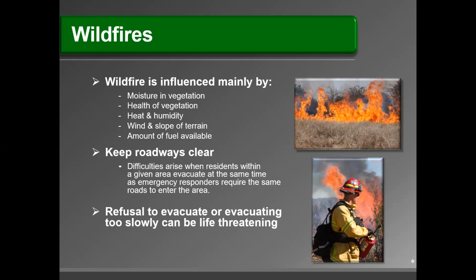And I'll tell you, as the fire department, we regulate that when we look at their inspections. They can only have a certain volume on site of a hazardous material in a commercial occupancy. As we saw on those signs back at the NFPA 704, the colored 3-4 signs, that's part of what that's monitoring. So where they have that paint can, that's a hazmat for us, so we need to know. We limit the volume to 55-gallon drums. So that's exactly what Ann's explaining.